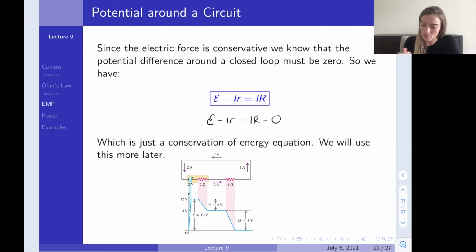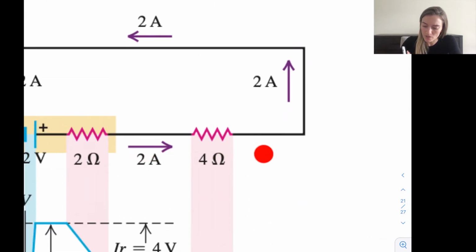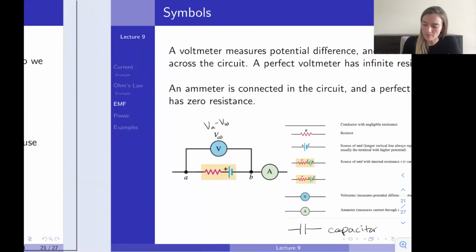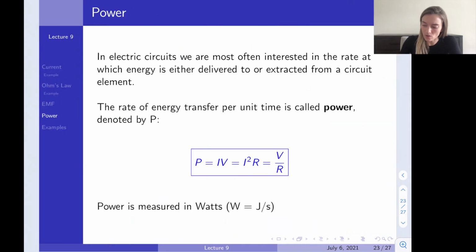So in the example of a resistor, the current through the resistor is 2 amps here. And then you would have to figure out, well, what's the voltage here and what's the voltage here? And that voltage difference you'll multiply by your current, and that will give you the power dissipated through this resistor. So we're obviously going to be doing examples with that. So that's how you would find the power dissipated, the energy per second dissipated through that resistor. Now, by using Ohm's law, you can get these other forms of power. And like I said, they're all the same.